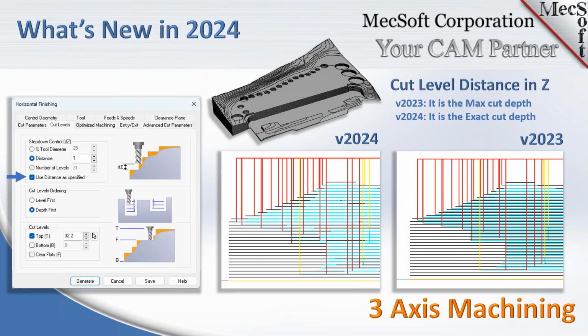Yes. So what the system was doing before was using the step-down control distance and computing an integral number of cuts between the top and the bottom Z levels. So you would always get a cut at the top, and you would always get a cut at the bottom.